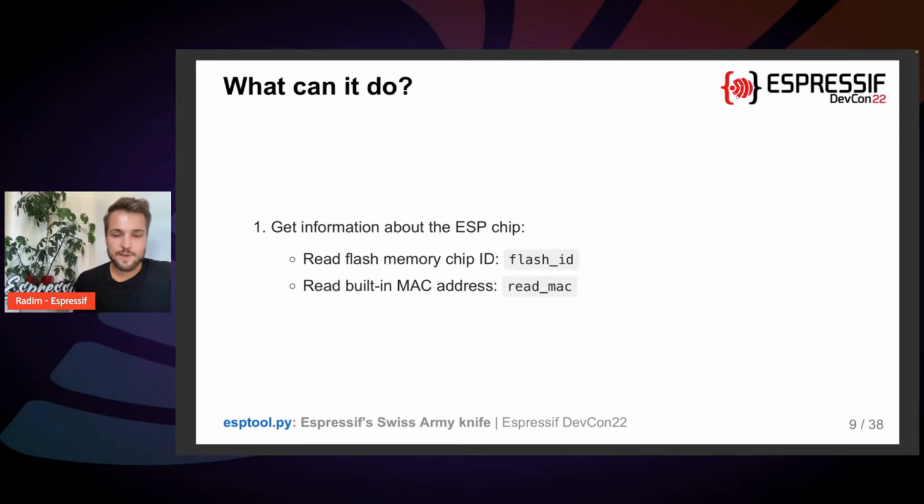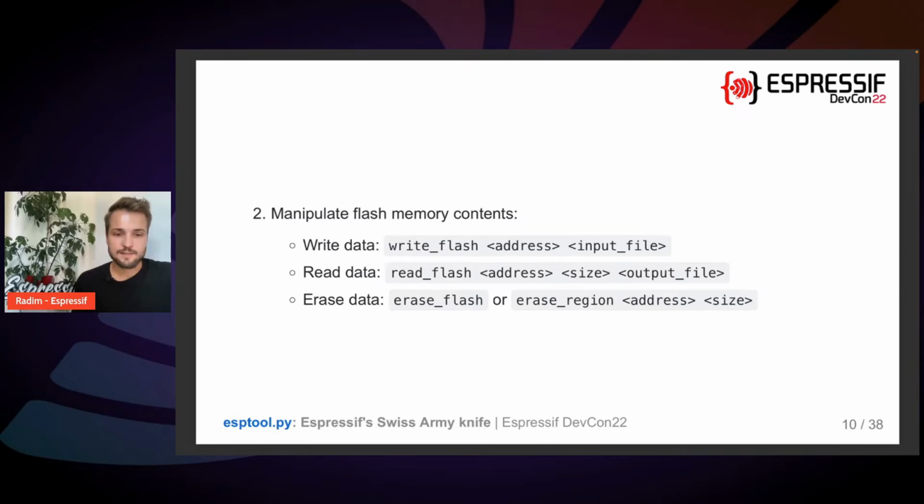The second command to get some information out of the chip is read_mac. Okay, next, esptool allows me, and I think this is the most important part of esptool.py, to manipulate flash memory contents. It allows me to write data, read data, or erase the flash memory.